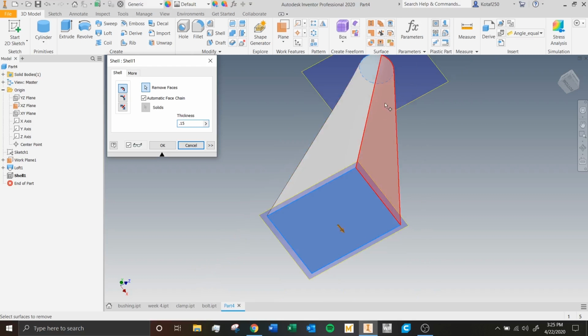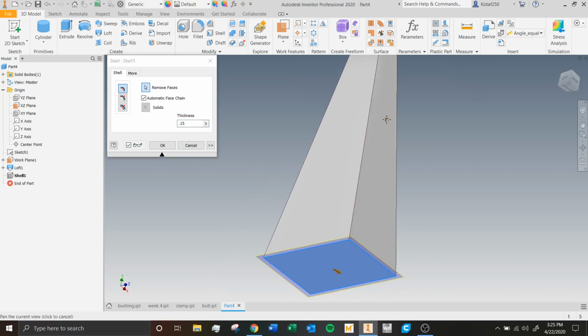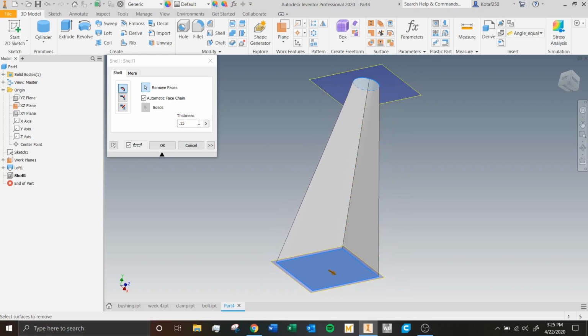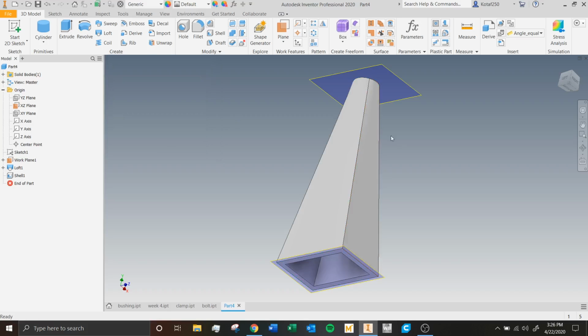See, I had to think about it. So the automatic limit it set was initially 0.1. But once I changed it to 0.15, that small change, it really did not like that. So if I change it to 0.15, it doesn't even want to do the shell anymore. So we're just going to stick with the original one we just had, even though we're going to be deleting this entire part here in a second. So that is how we get those.